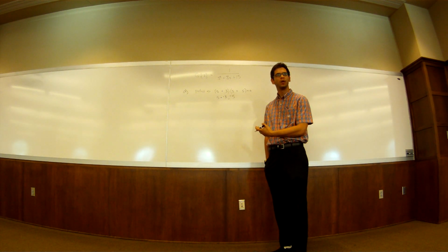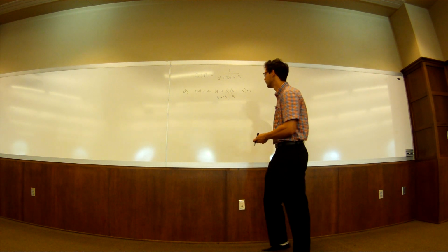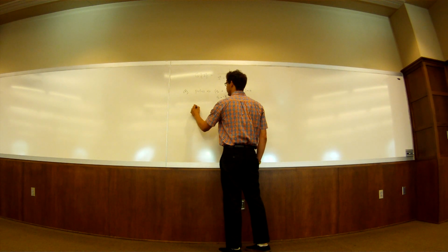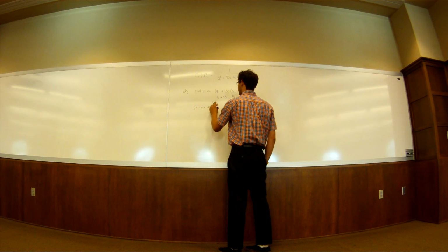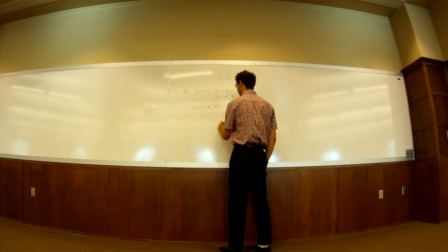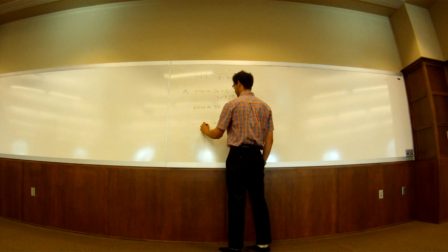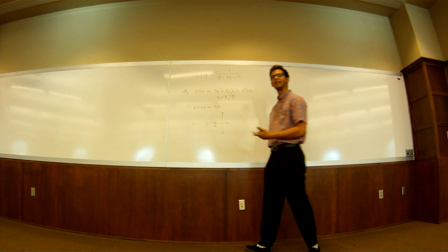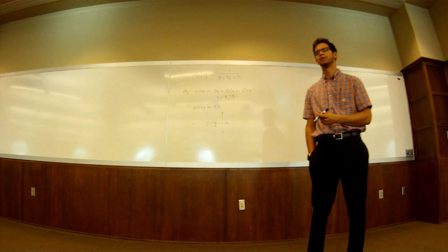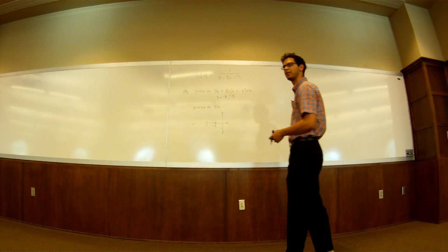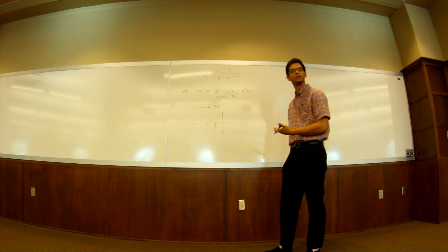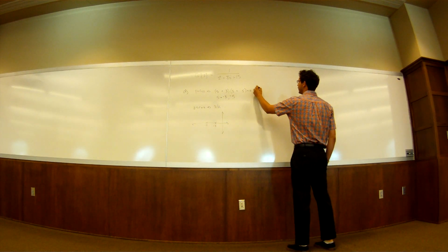So just by looking at the poles, what kind of system is this? Second order, overdamped, two real poles. Okay, cool. What are my zeros? None. If I draw my pole-zero map, what do I get? Is this stable? Yeah. How do you know? They're all in the left-hand plane. Perfect. Is that part A? Yep. All right, part B.